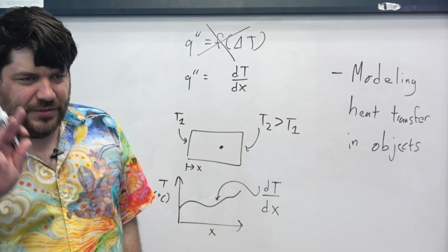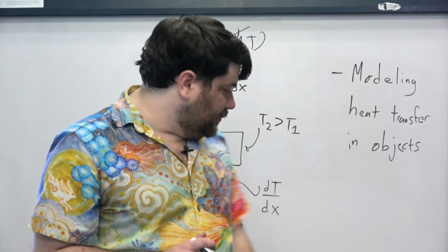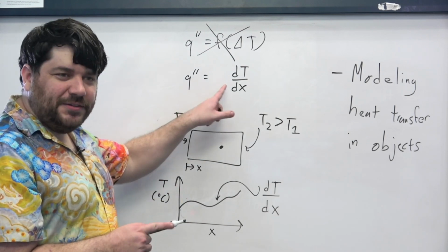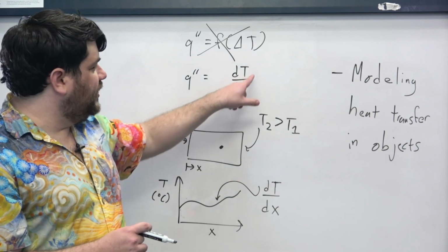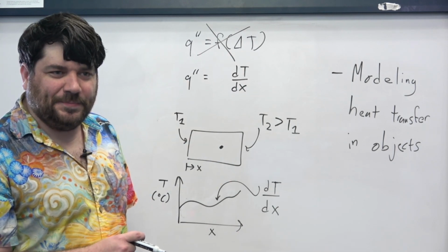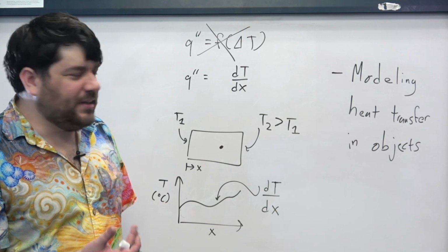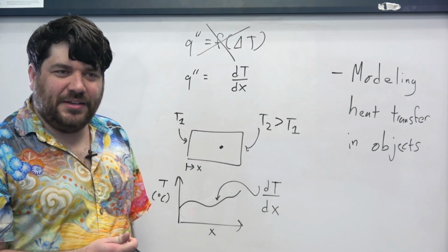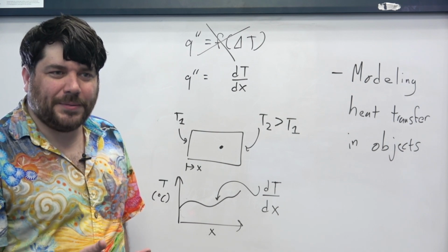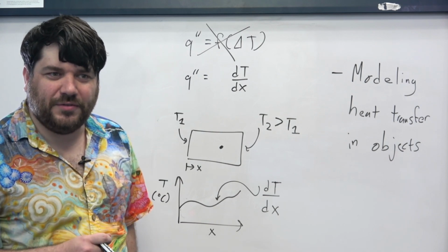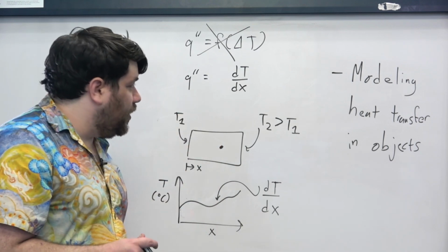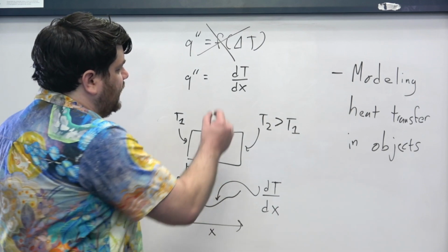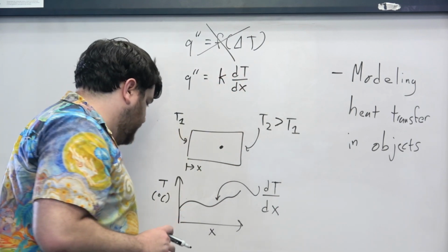Now there are two different subtleties that we have to consider when it comes to understanding what goes here. The first is that the units of dT/dx are not the same as the units of delta T. And what that winds up meaning is that whatever this constant is, it's not going to have the same units as the constant that we saw before, the heat transfer coefficient. The coefficient that's going to show up here will have different units, and as a result, we think of it as a different thing, and we call it a thermal conductivity k.